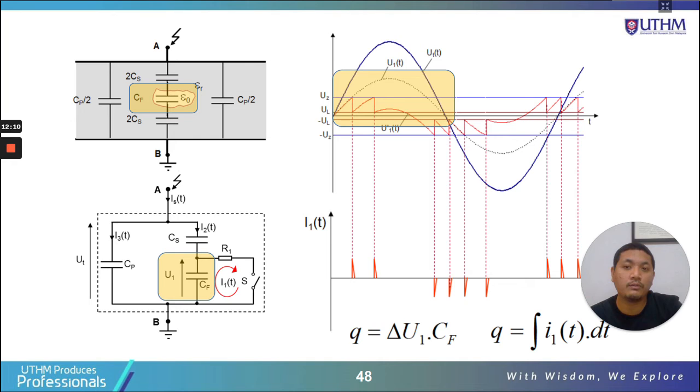However, if we have an air pocket, air is not a very strong insulating material compared to solid insulation, because air is just a gas. Solid has more strength in electrical breakdown. So the breakdown or electrical discharge will start from the air, in the void first.